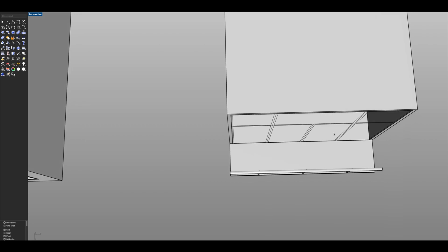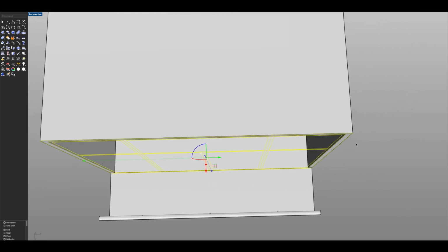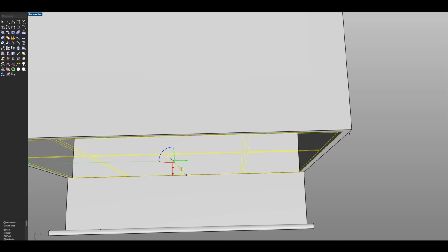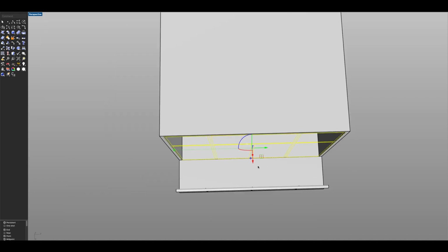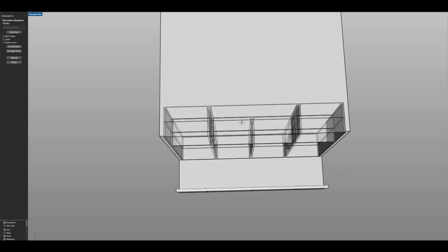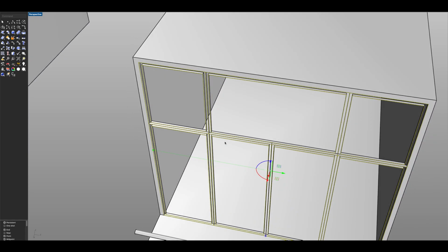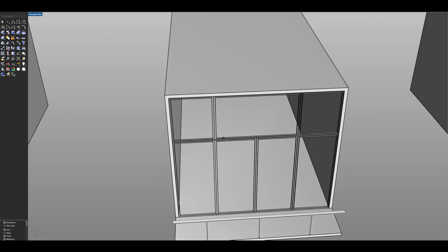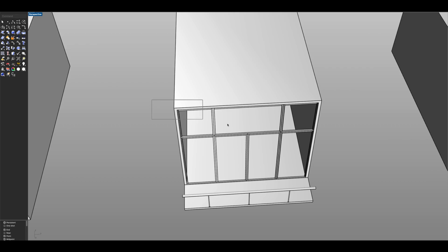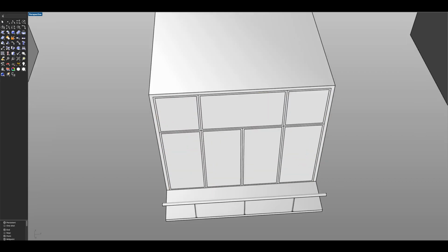Like that. Now from the top, once again, we can select all of these. We can deselect this one here, which we will not be needing, and then simply go for extrude curve. Same measurements, so 0.5, like that. Okay, we can now delete our curves. We can select everything again, and we can apply caps, like that.